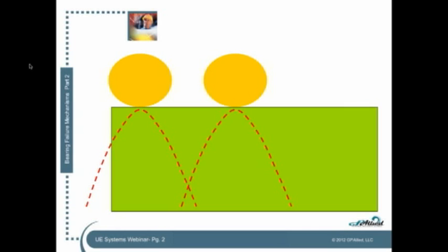It's a function of what does it look like at this moment. So if we know the number of rollers or balls, the roller or ball diameter, the pitch diameter, the contact angle of the bearing, and the shaft speed, then we can calculate the specific frequencies at which an inner race defect will show up, an outer race defect will show up, a defect on one of the balls or rollers, or a defect on the cage itself.